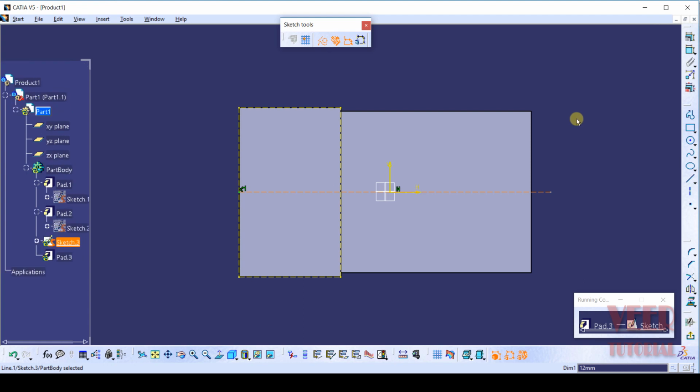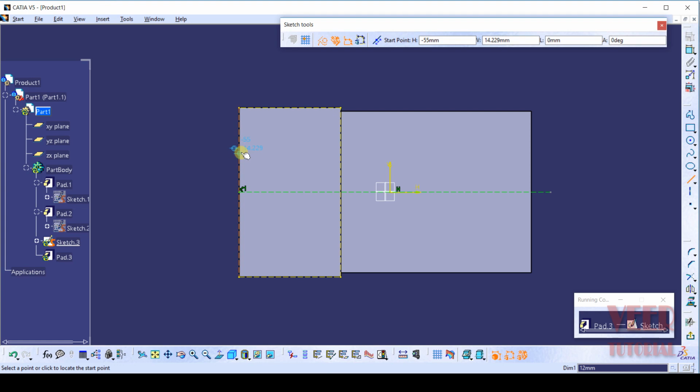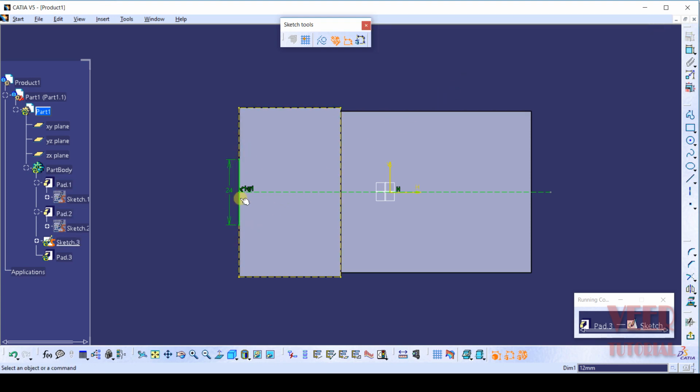After that line, we need to create our profile. So we know the value of the length. For this, I go to line once again, and then draw a line. Okay, make an uncheck on this construction mode. The length of the line on the left side we know that is 24. Okay, so press enter onto this and then click on symmetric extension. Click on this option. From this midpoint, draw a line like this. So it will create a line of 24 length.